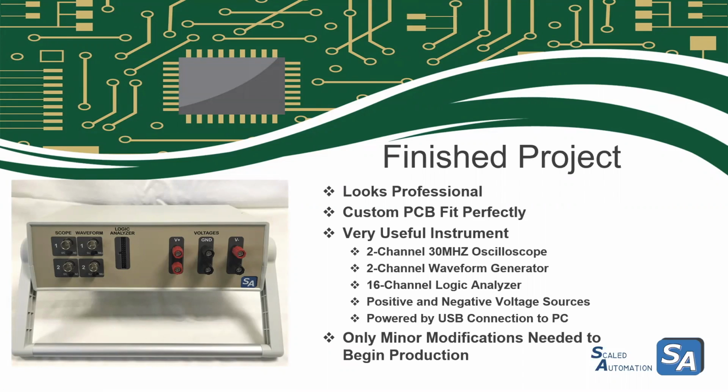It's a very useful instrument. 2-channel, 30 megahertz oscilloscope, 12-bit, by the way, not 8-bit like some of the cheaper ones. 2-channel waveform generator, and you have a variety of waveforms that will generate automatically through your control in the software. 16-channel logic analyzer, positive and negative controllable voltage sources, powered by the USB connection to the PC.